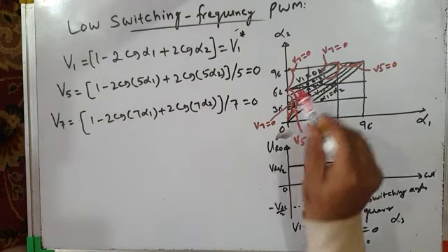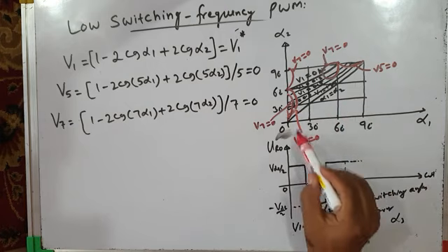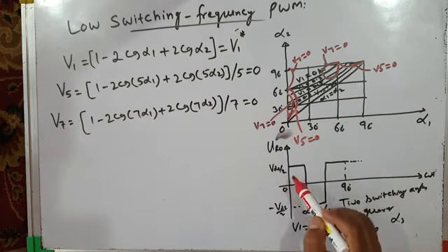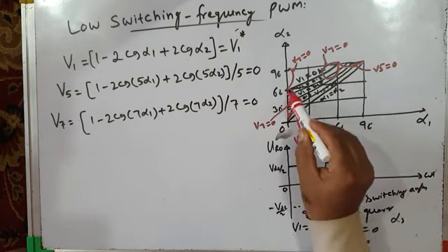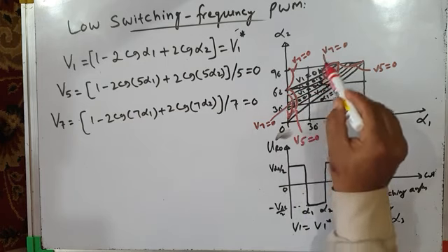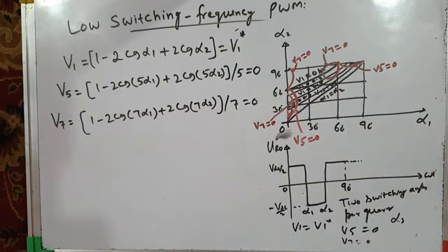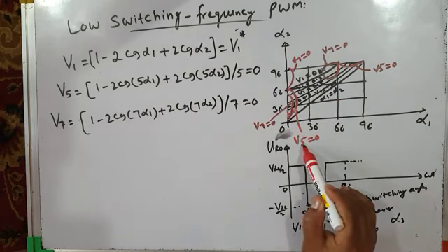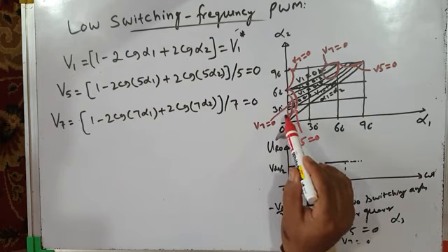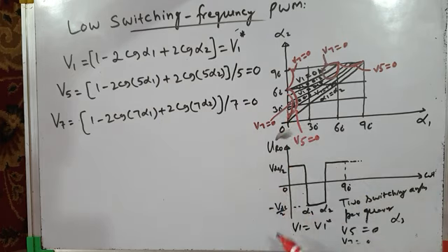We have got all these contours, V5 equal to 0 contours like this and like this, V7 equal to 0 contours like this, and this. We have done it in detail. Now, accordingly, V5 equal to 0 may be your requirement, or V7 equal to 0 may be your requirement. So accordingly, this is how you get it. Okay, so fine. So this is selective harmonic elimination.